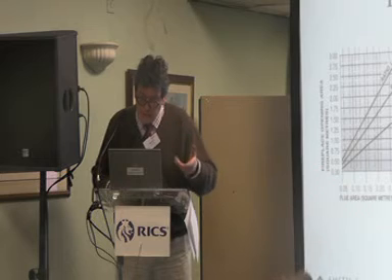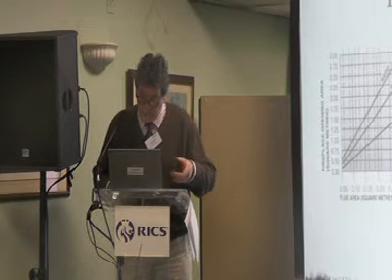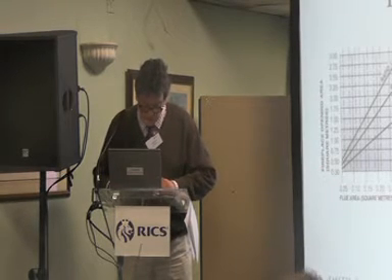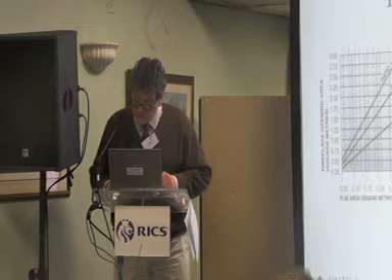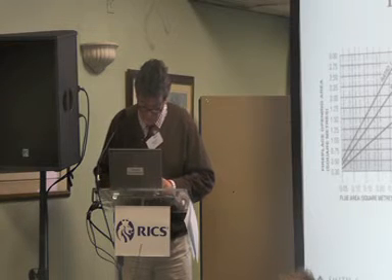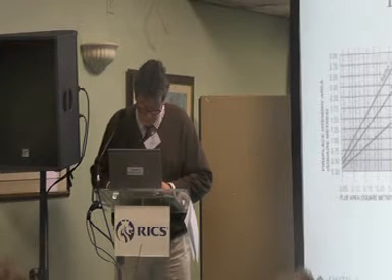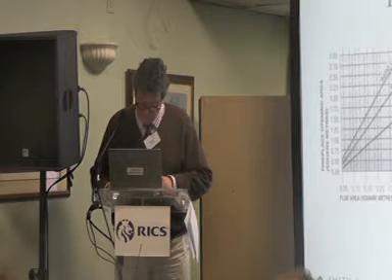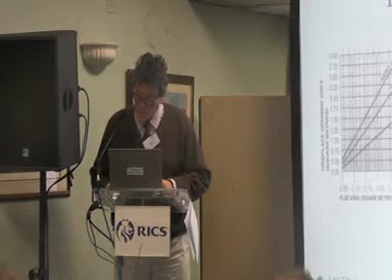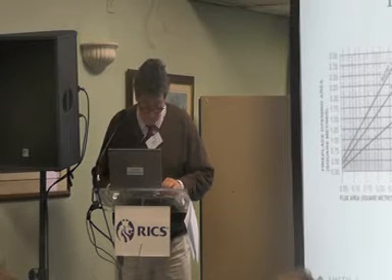So I'm trying here just to give you a few little helpful bits and bobs that you can take away with you. Stick to these ratios, and with a bit of luck your fireplace will not smoke. If it does, look further up the flue, look at the way the chimney is constructed, the pot's put on, the cowl is fitted, and all those kinds of things.